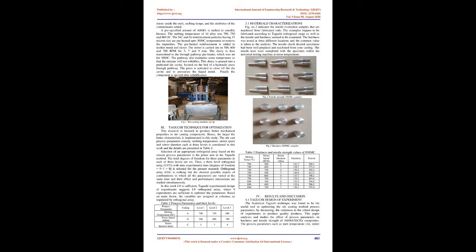GR is used for lubrication purposes. Alloy 6 reinforced composites increased the toughness, wear resistance and ductility. While GR reinforced metal matrix composite, MMC, offered poor strength and better wear resistance. Experimental procedure.